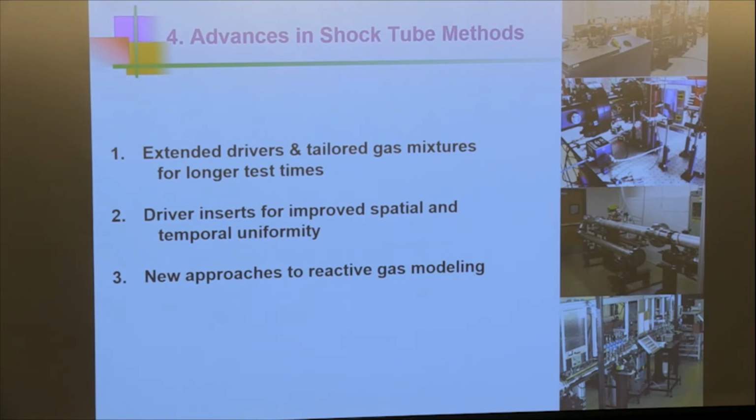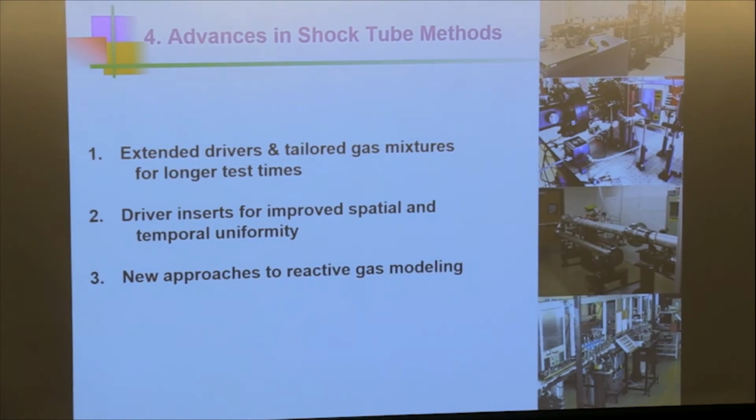It compresses the gas with a piston, but it doesn't do it instantaneously. It takes time to compress the gas to high pressures. And then they tend to be smaller devices, and they watch it for 100 or 200 milliseconds, during which time heat transfer takes place with the valves. So it's not an isothermal reactor. I'm kind of a non-RCM person. It's not an isothermal reactor, it's not instantaneous, but it has the virtue of getting to long times. And shock tubes generally didn't go to long times, but we've tried to fix that problem.